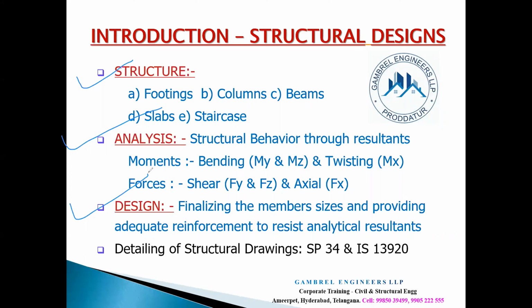Same concept, even for footing. The footing size and thickness have to be finalized, and reinforcement has to be provided to resist bending moments and forces, in the sense shear forces, one-way shear and two-way shear. So there is a little change in the analytical resemblance from element to element. When you identify the change in the design procedure, it becomes very easy to fix up the member sizes, right? I believe it is now a little clear to you what analysis and design are. Now let's go to the next slide.